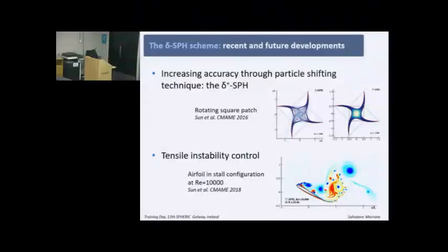And so here we would have a large negative pressure. And as Matteo showed you before, in the standard scheme, in the Delta-SPH scheme, you will have a large void here, due always to that pressure times the gradient of gamma. Here in this paper, which was recently published, we added a small change in the pressure gradient to avoid this and to recover the correct solution.